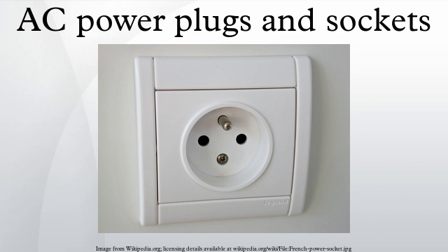Multi-standard sockets. Sockets that take a variety of plug types can be found in places where market size or local market conditions make a specific plug standard impractical to implement. Sockets may accept plugs to various European, Asian, North American, British or Australian standards, but not Indian or South African. Multi-standard sockets do not safeguard against devices being damaged by the wrong voltage. Users must know the voltage requirements of their appliances as well as the prevailing local voltage.